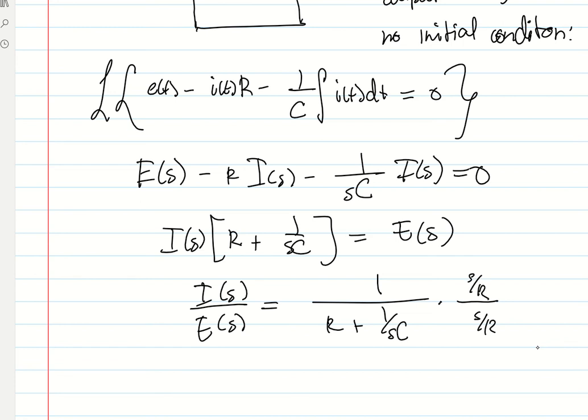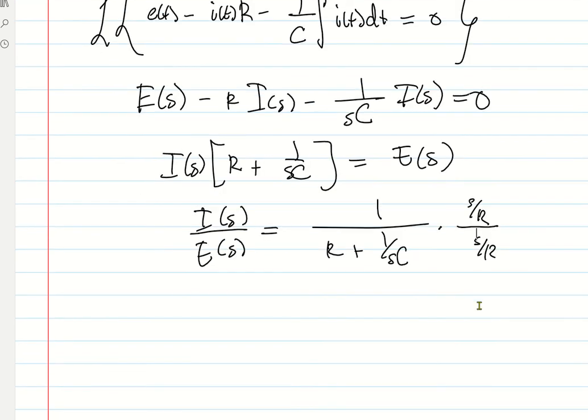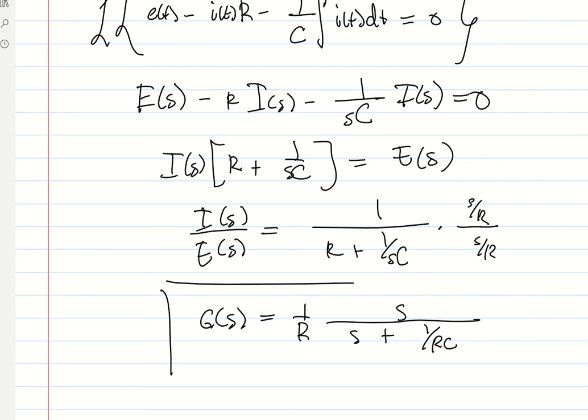So the transfer function G of S will be equal to 1 over R, then S, all over S plus 1 over R times C. And this will be our transfer function.